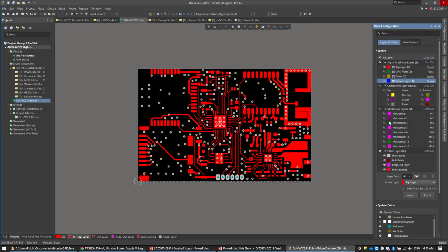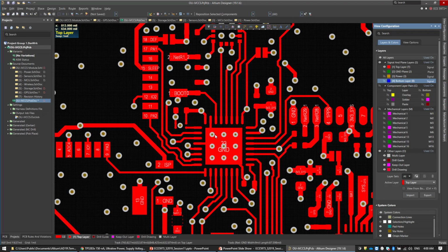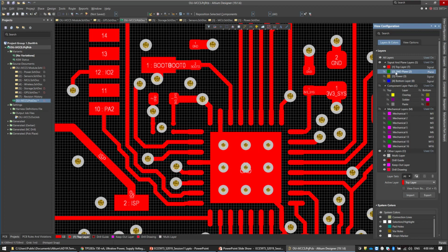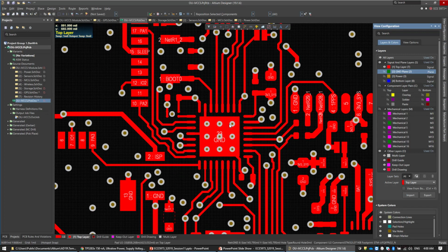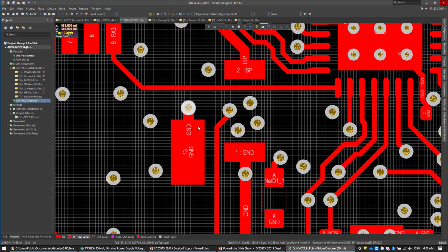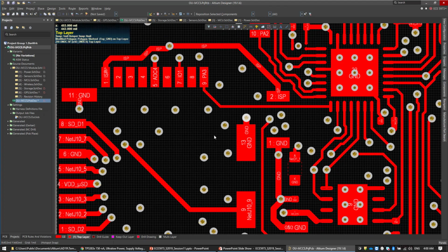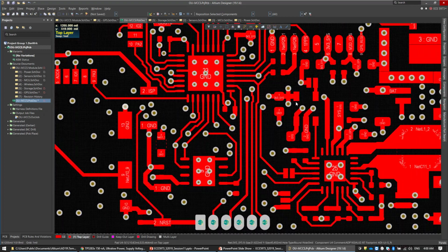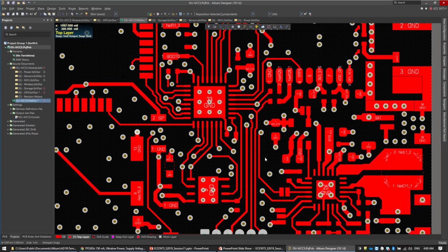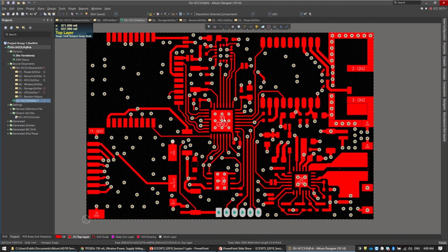So what is the secret behind that? It's the placement of the components, how you plan placing the components on the board. This is the secret. And you should not route any ground signal. Ground signals should be connected with vias, and they should be connected on the bottom layer. And how can you do that? You just fan out these ground paths by via and wire. Don't try to route the ground from point to point, point to point. You will complicate the board. Just place a via next to every single ground pad, and forget about it during the design, during the routing.